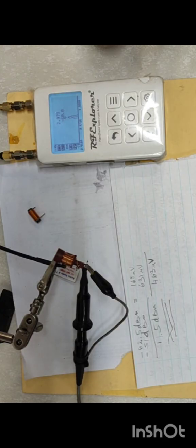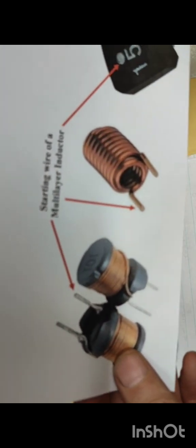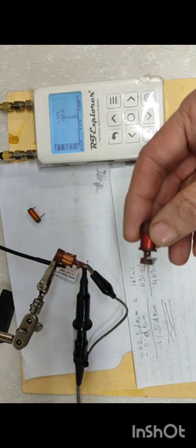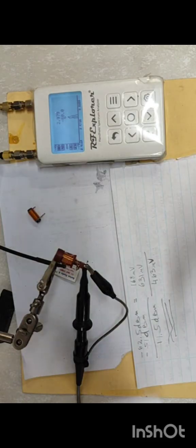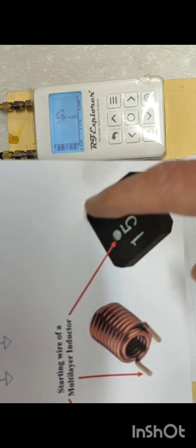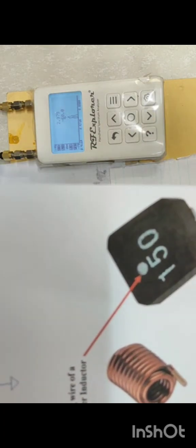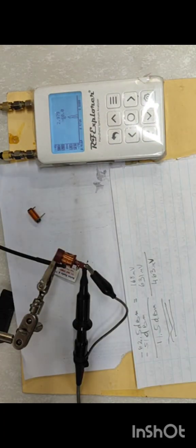It will be more in compliance with whether it's a European, American, or Chinese standard. Although it looks like a very simple thing, interference and noise have become extremely essential, because power supplies are becoming smaller and smaller and operating at much higher frequencies than in the olden days. Whether it's an inductor like this, or a blown up picture, or a 3mm inductor, once it's a multi-layer inductor, it is very essential which way you connect it up in your electronic circuitry.